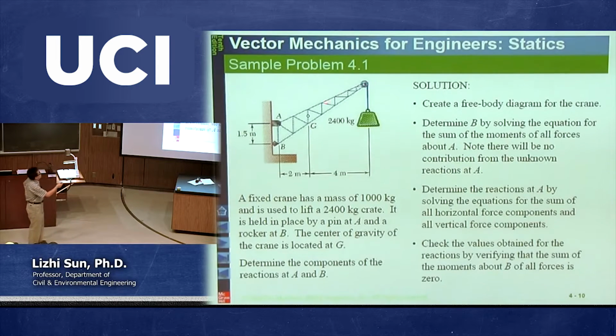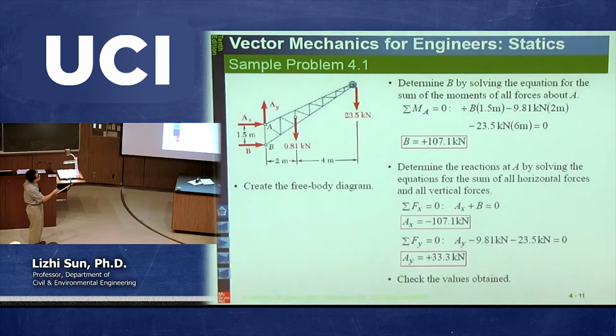Now, this rigid body has a self-weight. It has a mass of 1,000 kilograms located at point G. So in other words, you need to plot a force going down, because this is remotely interacting with the Earth using what we call the self-weight. So then 1,000 multiplied by 9.81, you finally end up with 9.81 kilonewton.